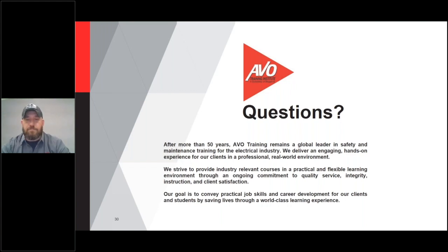Another question is, since the VCB has so much less mass than other types, air, oil, SF6, are they usually longer lasting for a number of operations? Well, really what it comes down to is use. How often is that interrupter used? We're talking directly here, with this question, about a vacuum circuit breaker. How often does it get used? What is it protecting? Are there a lot of problems out there as far as it opening and closing under load or under a fault? So each piece of equipment is going to be correlated to what it's protecting and what's out there in the field. Each system's got a history behind it.